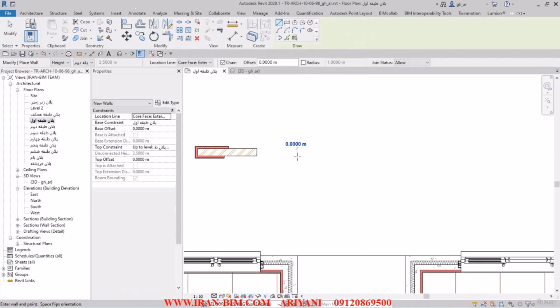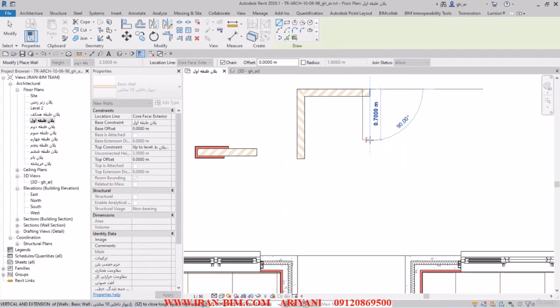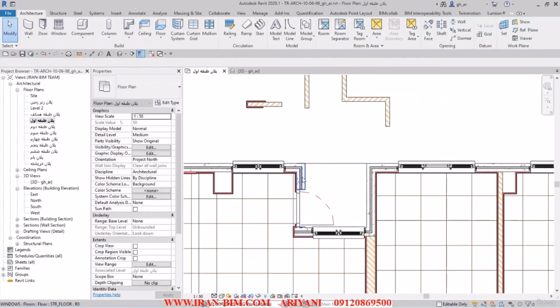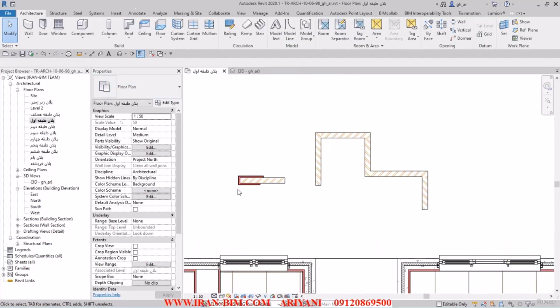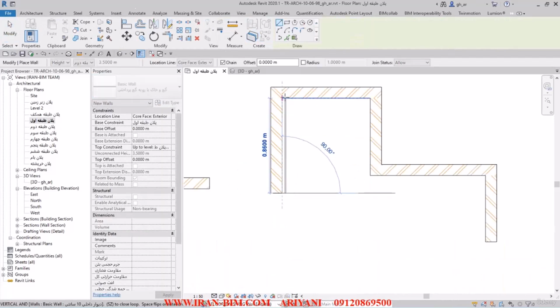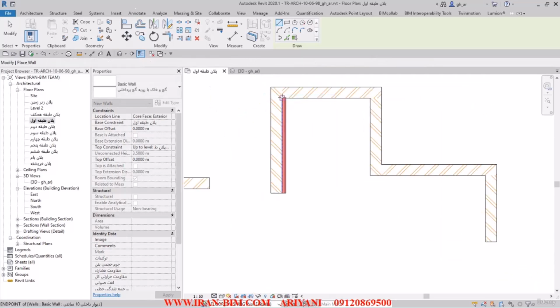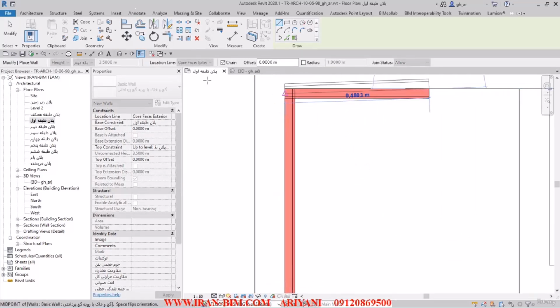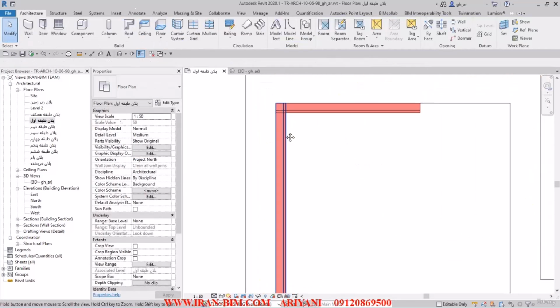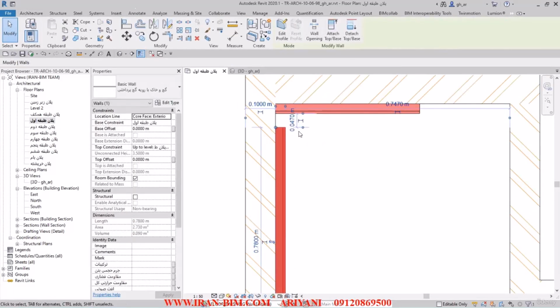The next one is when you, let me select the wall here and create similar. Let me draw this here and then here. So there we go. We said we can rotate the joinery around the wall, but when you're drawing the joinery around the wall here, as you can see, it doesn't join up by itself automatically. You have to do it yourself, and this is how it actually looks. So you have to drag this out yourself and then do the trimming.